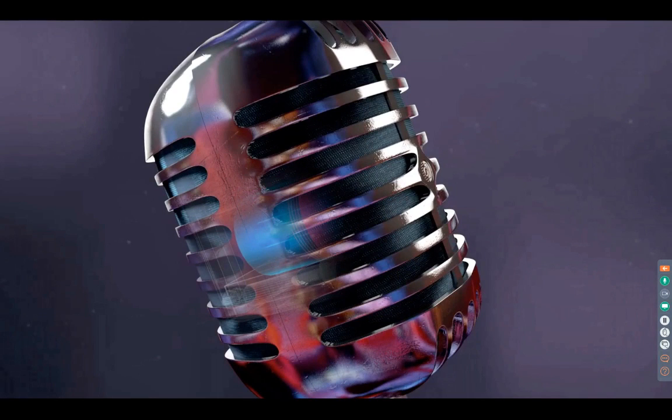But that actually makes a microphone omnidirectional when you do that. Yeah. So if you want an omnidirectional mic, you just close off the back, and basically through the process of diffraction, anything that's around that microphone will impinge upon the front of the diaphragm and cause it to move. So that's what happens when you cup the grill of the mic.